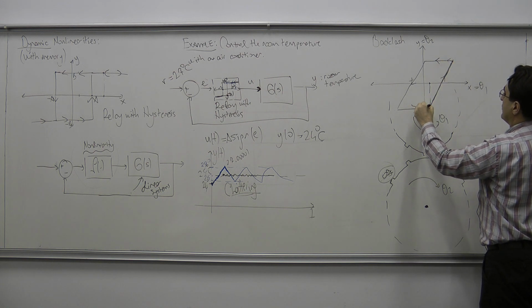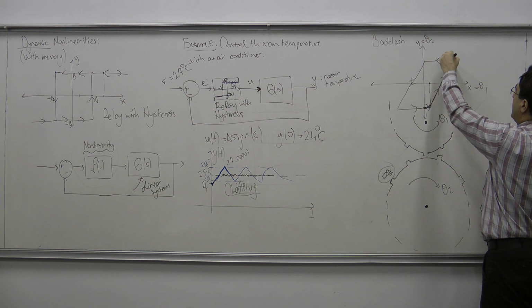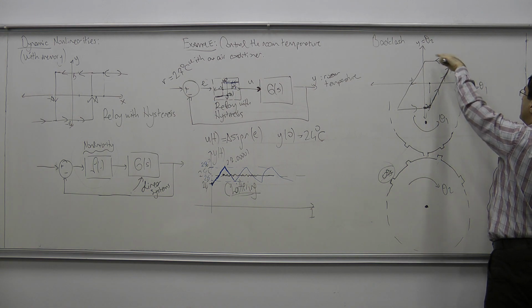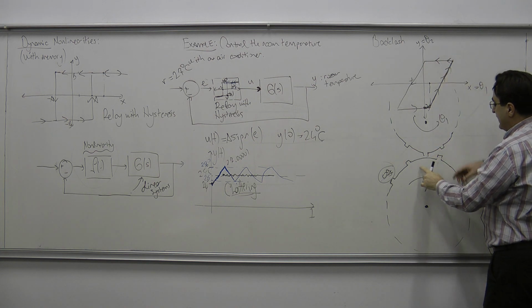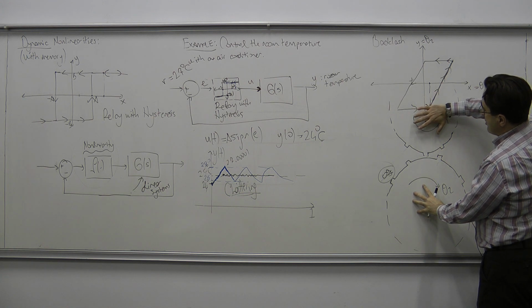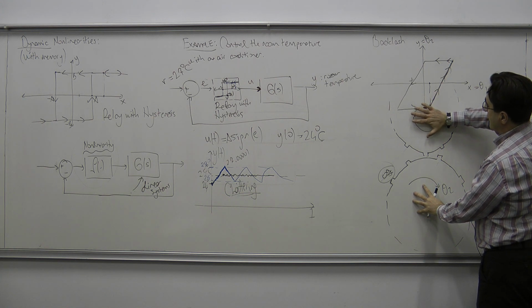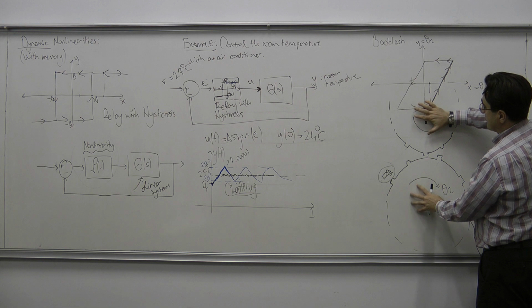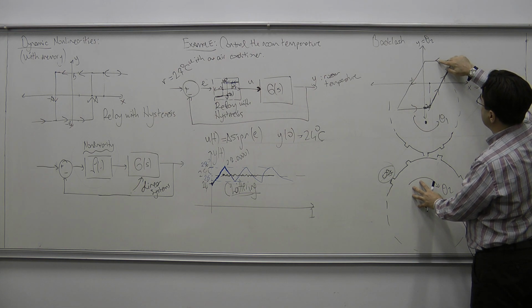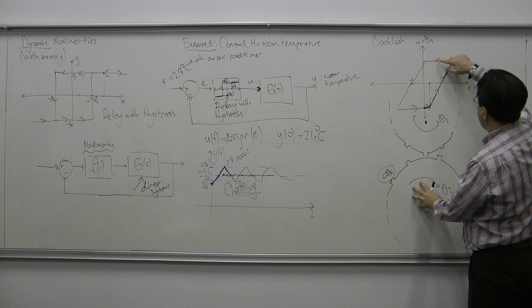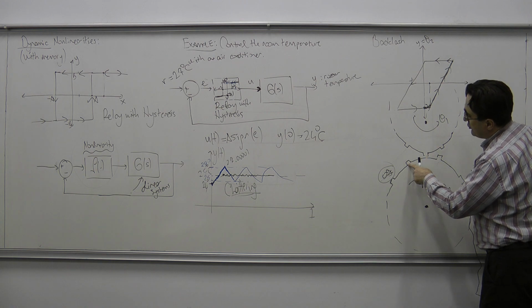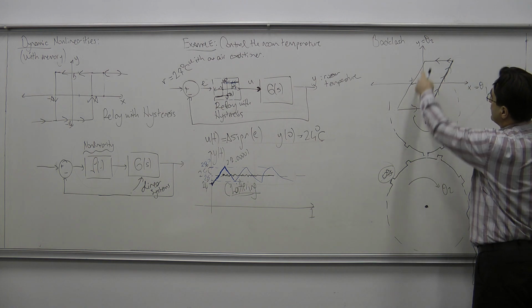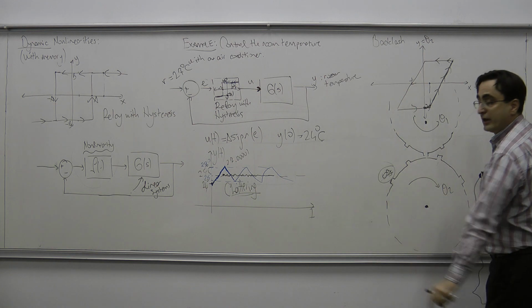So we started from here, and then we came here, and now we are reversing theta 1 in the other direction, and then this gear stops turning because the cogs are separated again. Okay? When I start turning this clockwise, the second gear is going to stop turning. So it's going to remain constant for some values of theta 1, and only when this cog reaches this cog are we going to start having a decrease in theta 2.